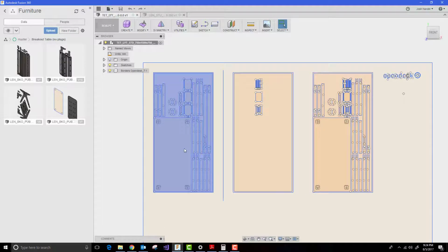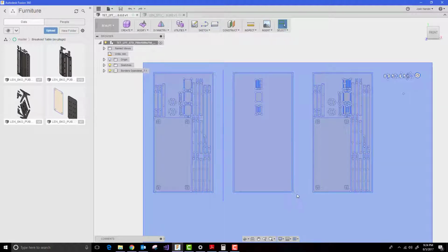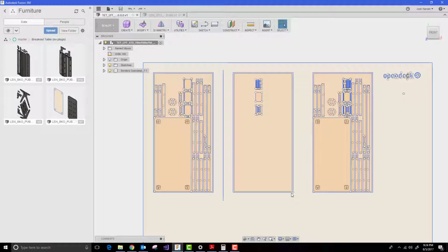So I can CAD out sheet 1, and I can CAD out sheet 2. I can do my CAM for sheet 1, and as long as I leave my origin in the same corner, and I literally just flip the sheet of plywood over on its axis, the long axis, then the origin stays the same, and I cut again, and it cuts right in the right spot.